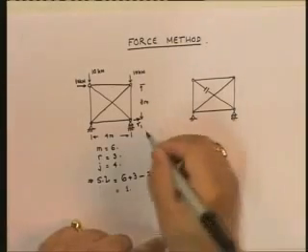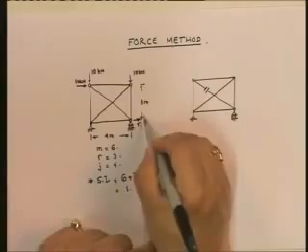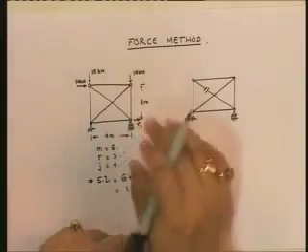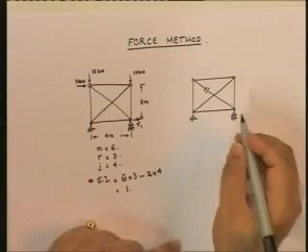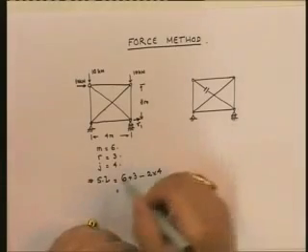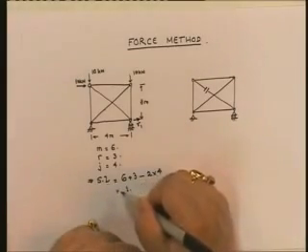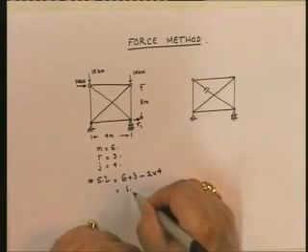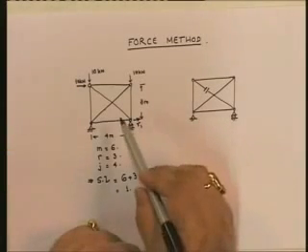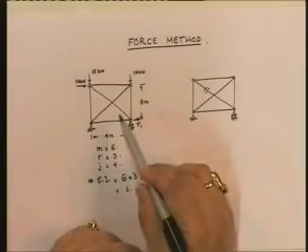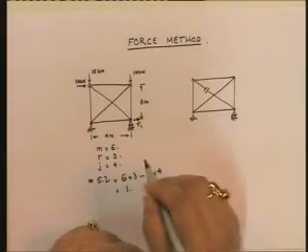Okay. For now, let us forget about finding out this displacement. We will find out this displacement later on. Okay. Let us now first find out all the forces in all the members. Now, obviously, since it is a statically indeterminate structure, you cannot find out all the forces in all the members using just the pure equations of equilibrium.